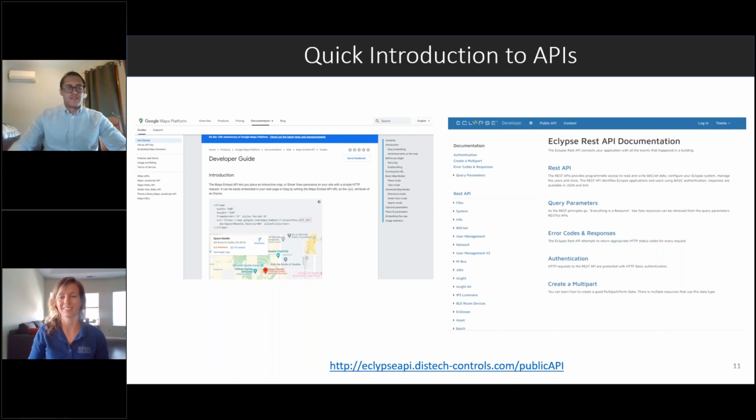So what you would need is something in between, which we label as a gateway device. And that transitions the language from one to the next. It's the same as the translator on your phone, allowing you to translate one language to the other. The hardware that we described, the Niagara Jace, is an example of something that could be a gateway. It allows different languages to be sent to it, and then it's able to aggregate that data and transition it all to, let's say, BACnet protocol, so you can read it all in BACnet.